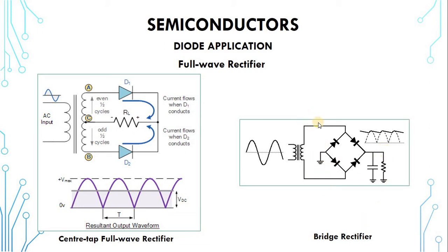And when this side is negative and this is positive, this conducts the positive here, and then this one conducts the negative to ground. So realize that for all the cycles of the input, the load is seeing only positive here and negative here. At the end of the day, we have harnessed all the positive to here, and then we have the negative potential here. So the load sees positive here all the time, negative here, just like in this case.